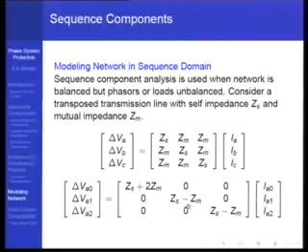In the normal case you are working only with positive sequence phasors. Do you see that clearly? Zero sequence excitation is not there, negative sequence excitation is not there, so you are working with positive sequence phasors. So when you look at a load flow, the data and so on, the transmission line impedance is so and so. It is not per phase impedance. Many people carry this impression that it is some per phase impedance and so on. It's not that. It's a positive sequence impedance that you are using. What you are getting there is ZS minus ZM. That is the data which you are getting.